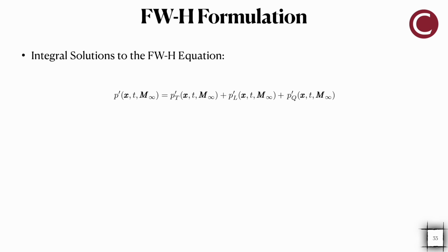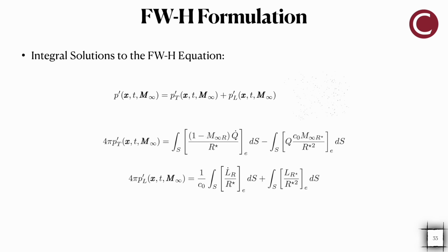So the first two terms are the thickness and loading pressure terms, which are just simple surface integration. But the last term is a volume integration, which is computationally very expensive. So we can neglect that term if we include all the nonlinear flow field and the noise sources within the data surface that we choose. And after implementing our acoustic solver, we need to validate it.